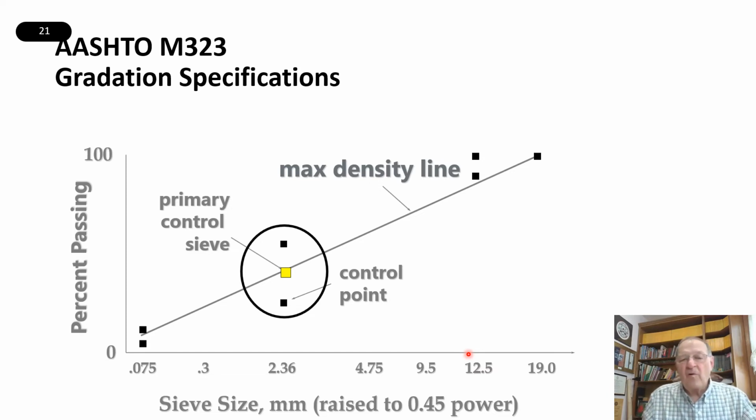So for a 12.5 nominal maximum size mixture, where I have 12.5 millimeter rocks, 1, 2, 3, and then a fourth one to go on top. And of course, rocks aren't all the same dimensions. They're not like balls. So you'd have to do it with a bunch of sets of 4 rocks.